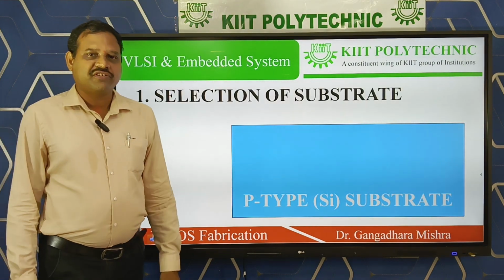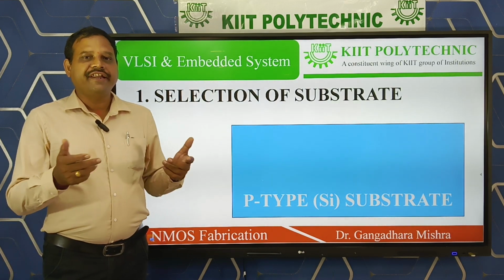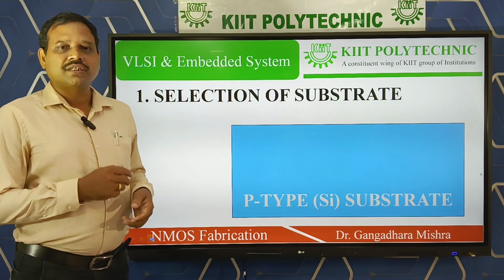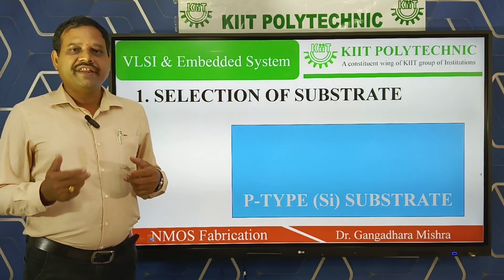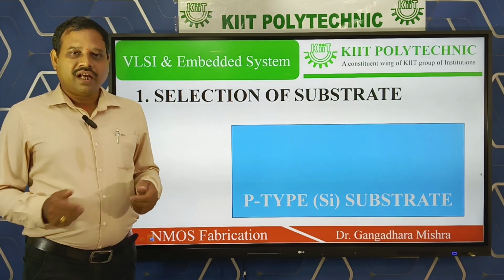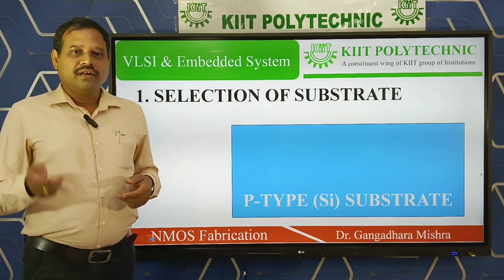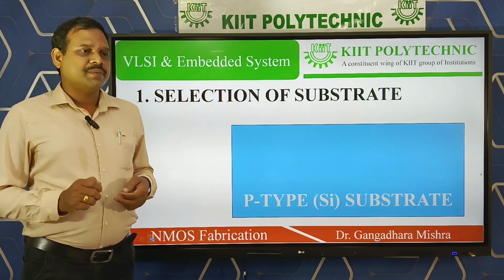To begin with the process, we first select what type of semiconductor material we need as the base material or substrate. In order to fabricate an NMOS transistor, we need to take p-type silicon as the substrate, and on the contrary, if we are going to fabricate a PMOS, we need to take an n-type semiconductor material.